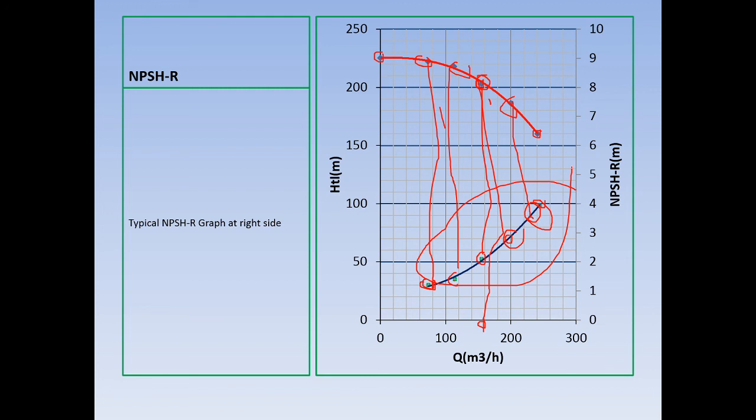And for example, NPSH required by your data sheet pump at that specific flow capacity is 5.25. You are still safe, but be careful. One day someone opens the valve, and then NPSH required is now higher than NPSH available. That's when the nightmare starts in your pump installation.